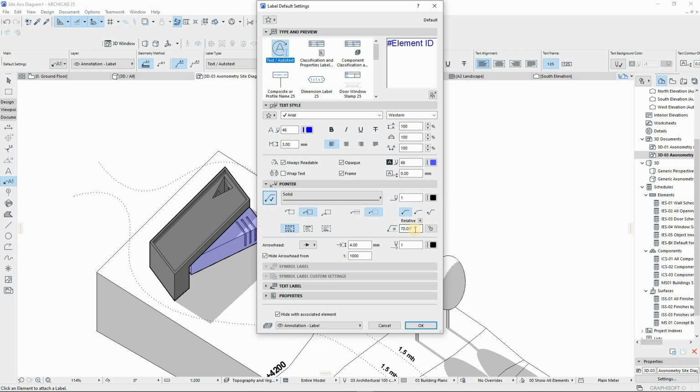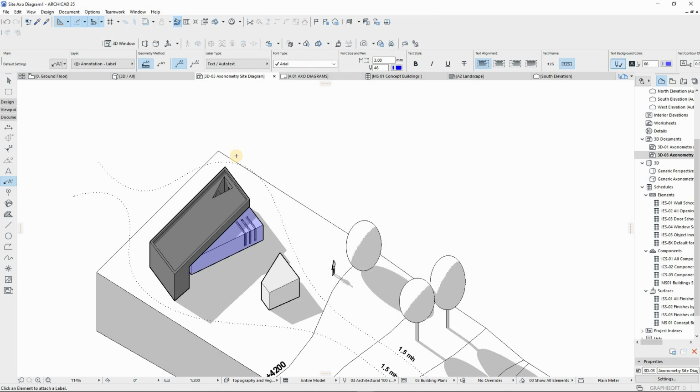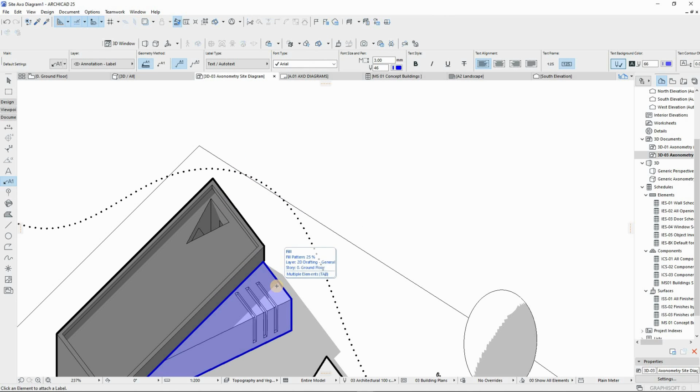Yeah, I think I'm good to go. So now let us place the fill. We have to pick the morph instead of the fill. So what to do, hit Tab on the keyboard. That will activate your morph, then click on your morph.